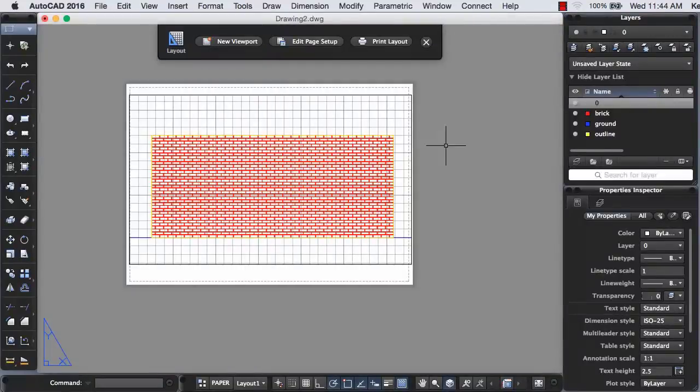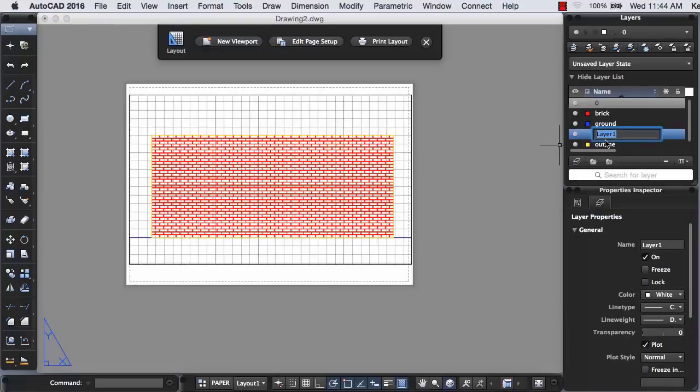So let's go back to AutoCAD. One thing I normally do is create at least one layer, I'll do it here, that I call no plot. And I'll give it some color that I know. All right, so the no plot layer, when I have it selected, I want it to not print, so I'm going to come down here and where this plot is, remove this checkbox. And you should at some point have a little icon show up that makes it look like it's not going to print. There it is. It's just too big. So that tells you that that layer is not going to print, which is good.